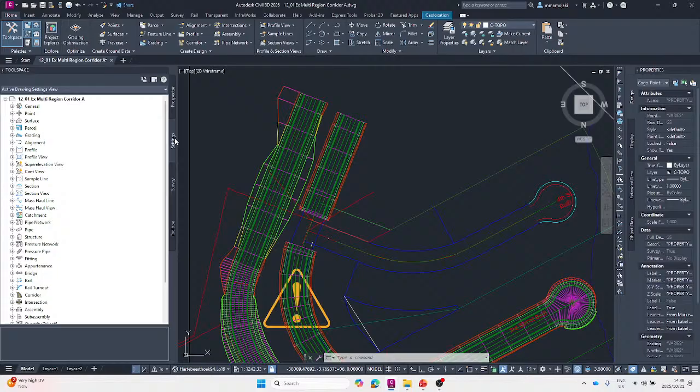Now, the settings tab. On the settings tab, there are generally three levels of settings within your drawing. So the first setting, usually it is your drawing settings. If you click there or right click on the drawing name itself, you will be able to edit drawing settings, or edit label style defaults, or edit LandXML settings, and then your table tag numbering if need be.